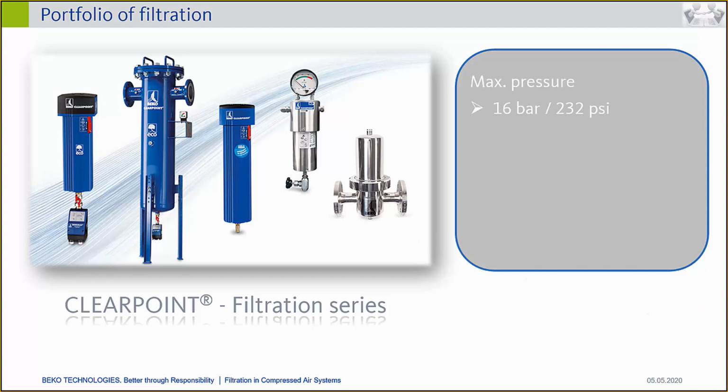The pressures which can be used are a maximum of 16 bar or 232 psi for the threaded versions. They can also go up to 50 bar. In case they have the 50 bar version, you have a different thread connection here between head and housing, but from the outside they look totally the same.